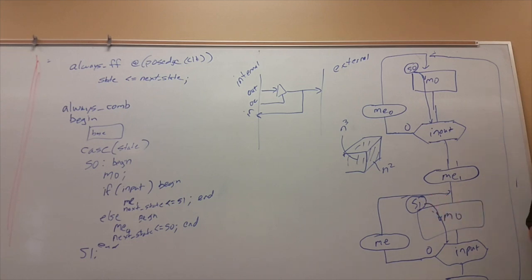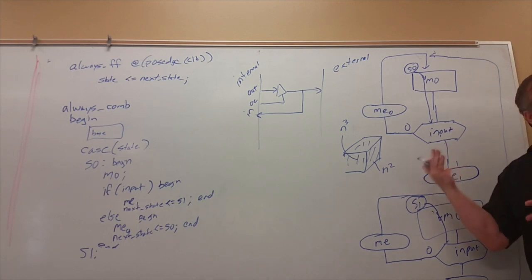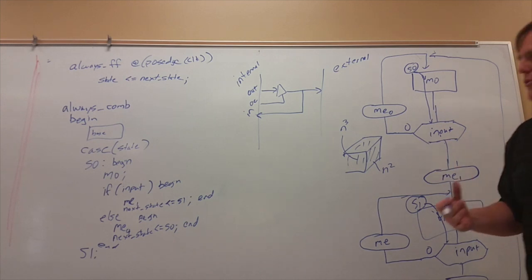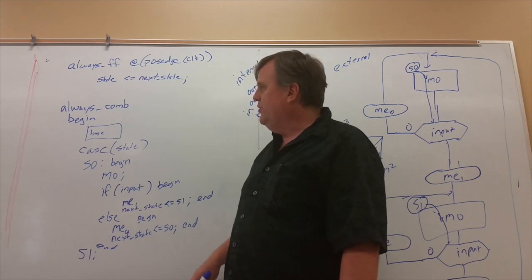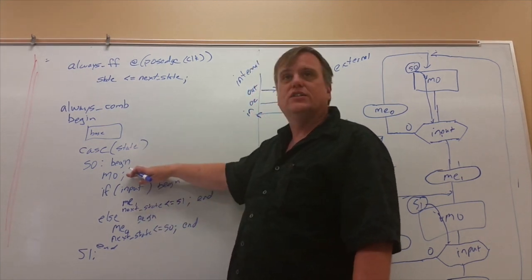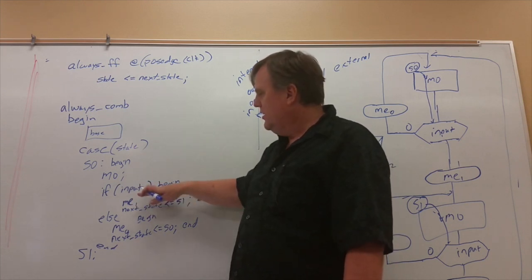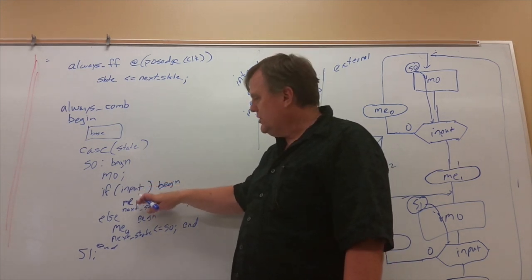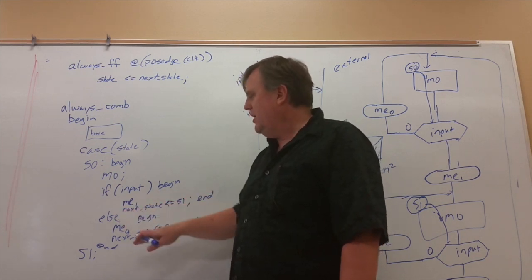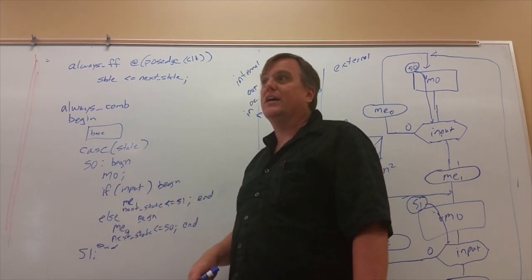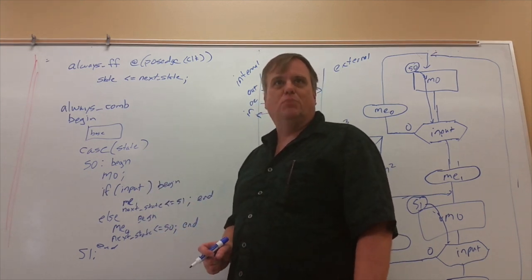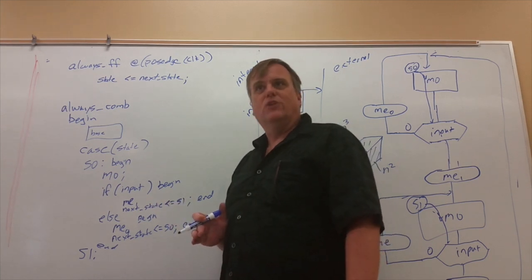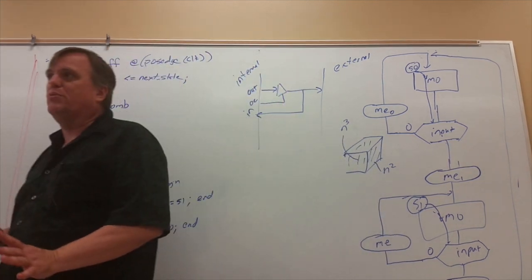Done. See how nice and easy it is to go from this to code? The other nice thing is if you write your code this way, it's really easy to walk through. You can just take a look: oh, initial conditions. This is what's set in the state block. Here's my first decision block. Here's what's in the conditional block afterwards. Here's my other line. Here's what's in its conditional block. You can walk through your code and generate the ASM trivially if you write the block code nicely. That's really nice for documentation purposes.